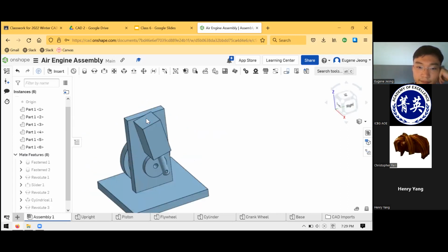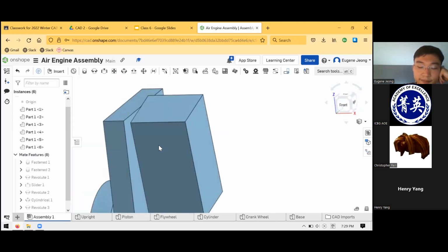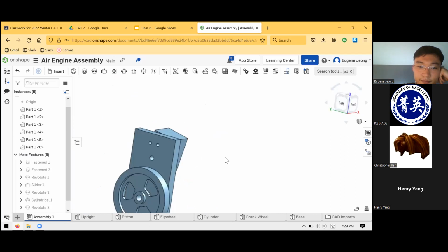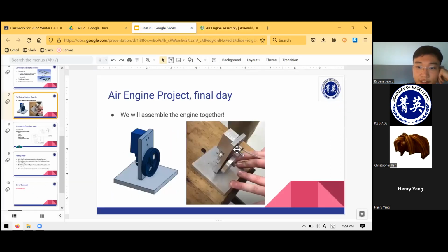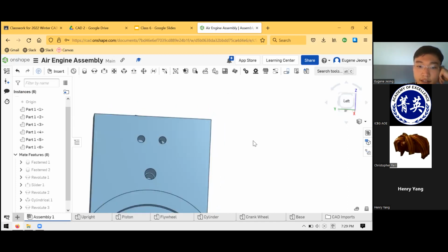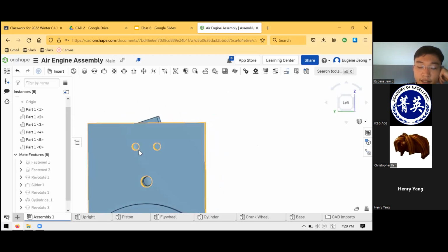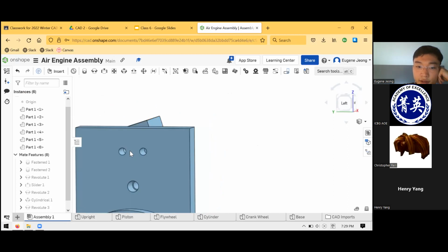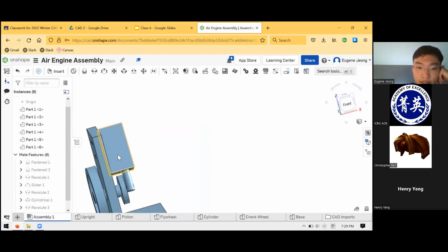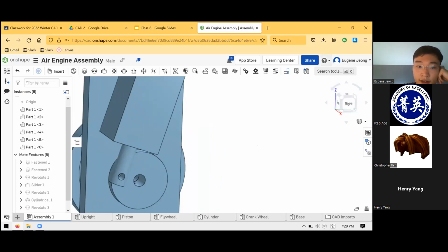And the way that works, you can see in the image, through one of the sides, that's your inlet for the air. So let's say it's this side. So when these two holes line up, the air is going into the cylinder. And as that happens, the pressure of the air is going to push this cylinder out further.